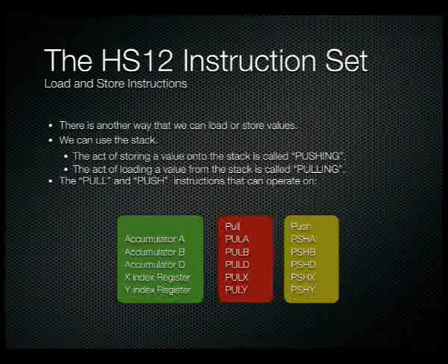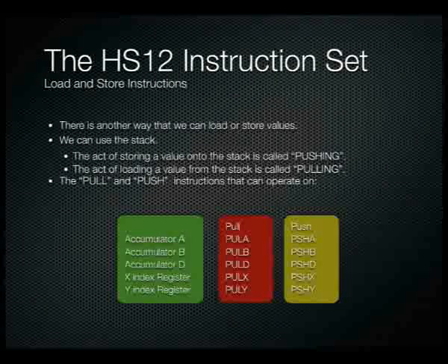So we can use the load and store commands to get data in and out of our processor, but there are also other ways that we can move our data in and out of the processor. If we temporarily want to preserve a value in a register, but we're going to need it later on, so there's no real point in sticking it in a particular variable because we're going to need it in a few instruction cycles' time, we can actually use the stack.